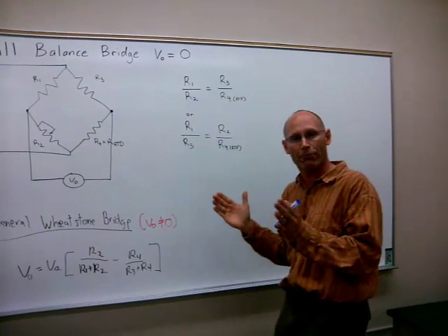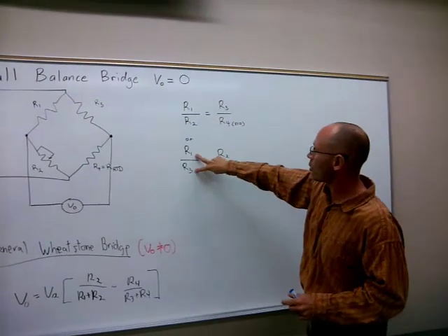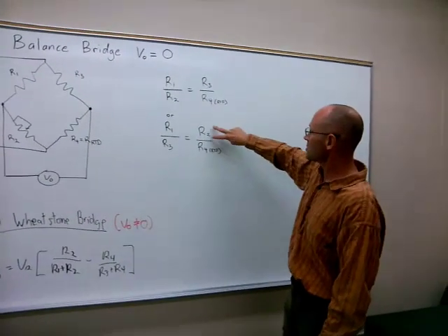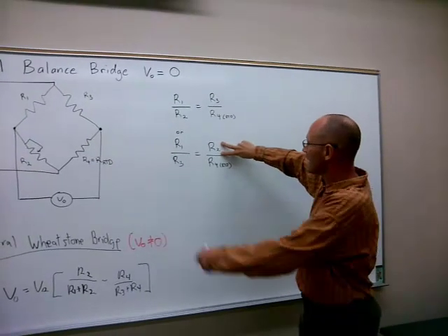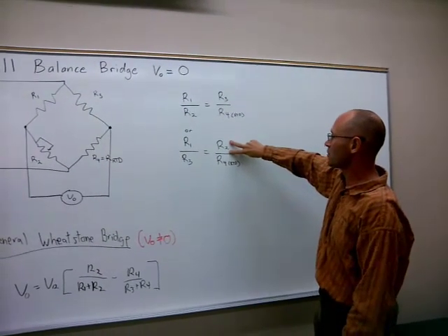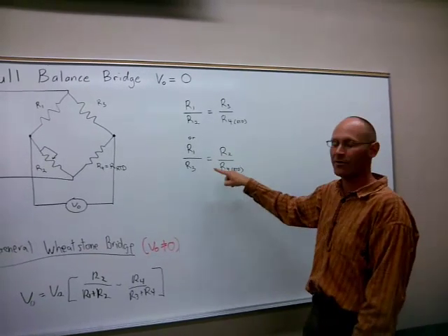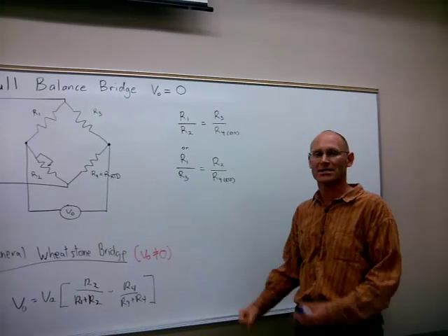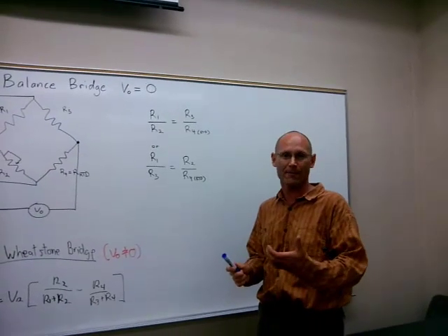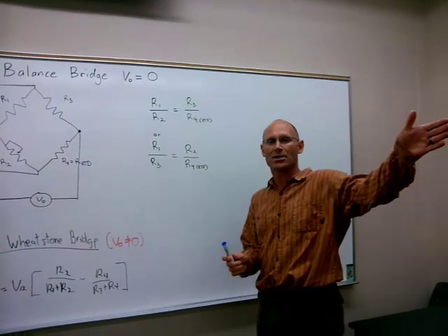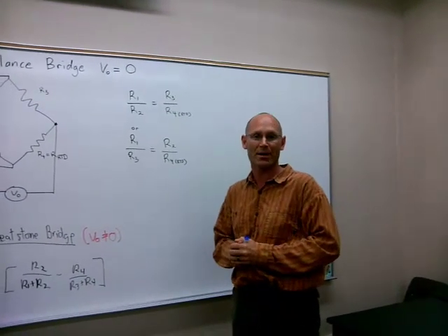But what's really important about this is, remember, R1 and R3 are fixed. This one we are adjusting, and we know what value it is. And once we have that, we have one unknown. And we can calculate the resistance of R4, and that resistance is going to correlate to a very specific temperature value that's cited through an equation that we can use from the manufacturer.